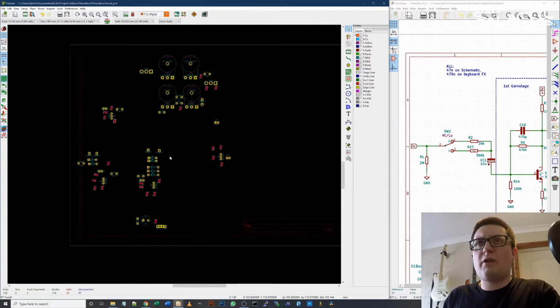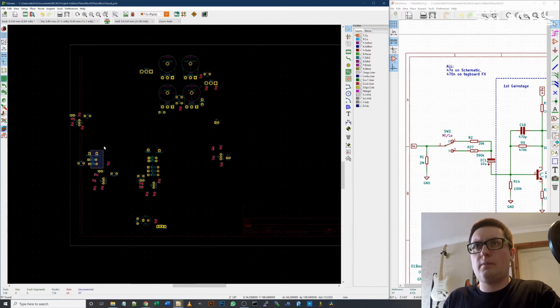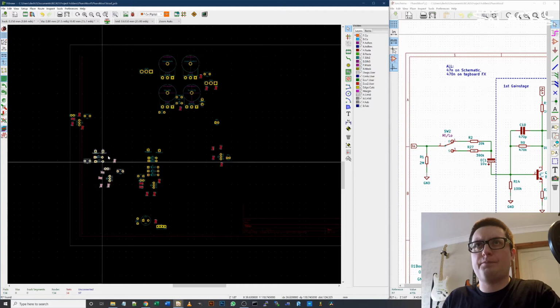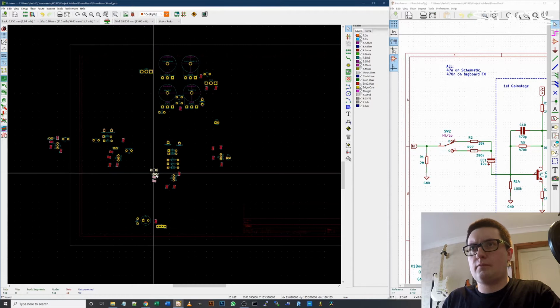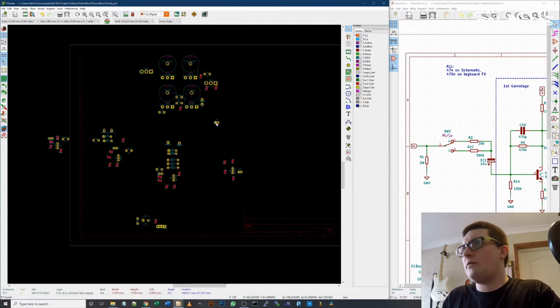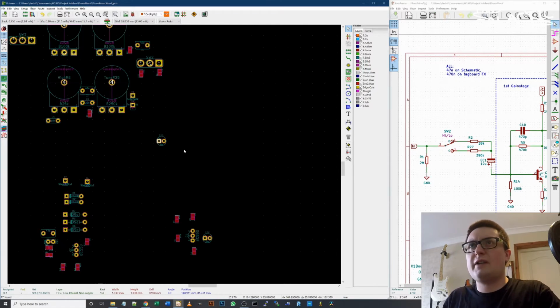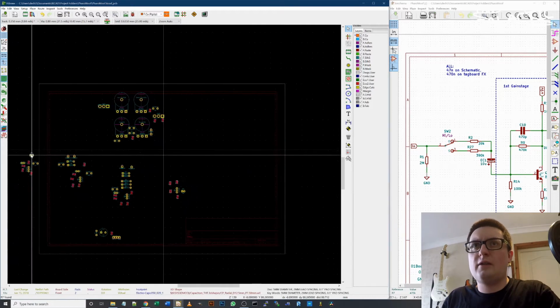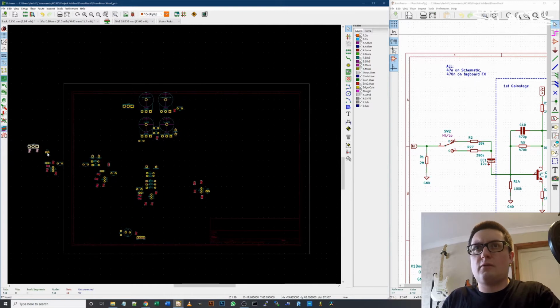Okay, so we have our rough functional blocks. We've got gain stage 1, gain stage 2, gain stage 3, and this last gain stage 4. Where's that cut from? Oh, that just goes after this high-low input switch before the first gain stage. So that's going to join that switch through there.